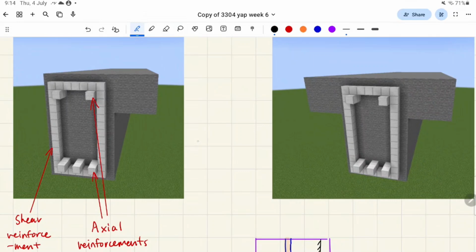So let's just draw a continuous beam, for example. Yeah, that's right. Okay, all good. So we have areas in a continuous beam where we have positive and negative moments, right? Where there's a negative moment, this is called hogging. This is the consultant lingo, Dom, essentially. And then these areas of positive moment are called sagging, right?